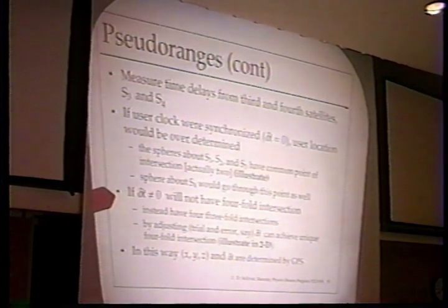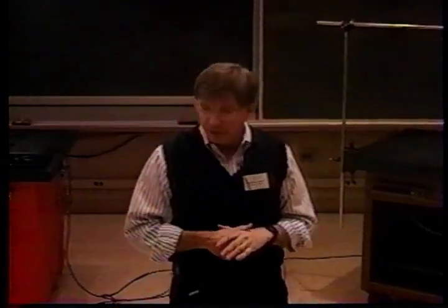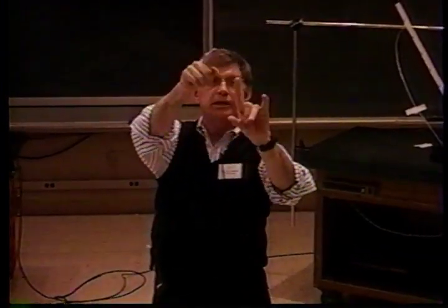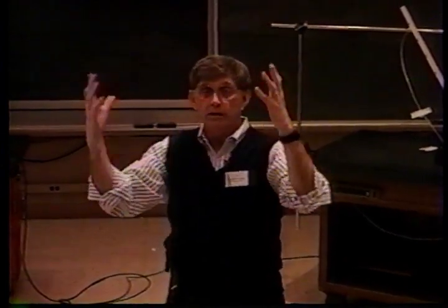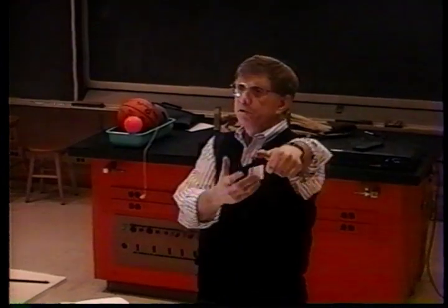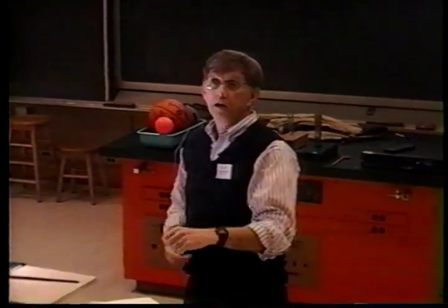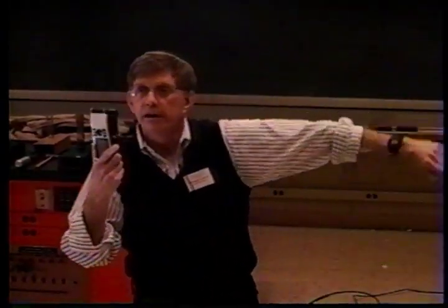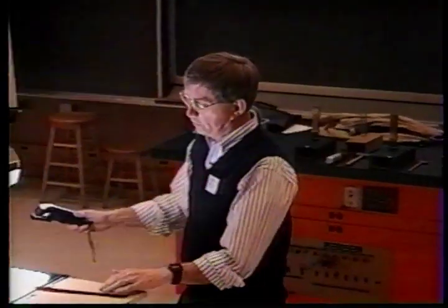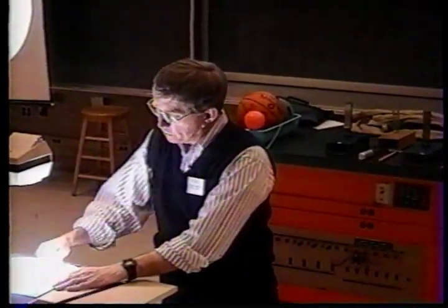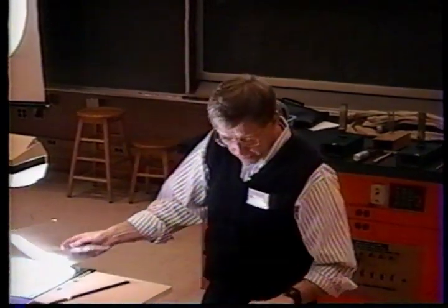And so in that way, you learn from 4 measurements, you learn 4 things, and you should from 4 independent measurements. You learn your x, your y, your z, and the clock error. So now you've got a clock that's as good as the atomic clocks up in the satellites at the price of your $30 wristwatch. The receivers, GPS receivers, mine included, have clocks that are no better than the clock on my wristwatch here. Don't have to be fancy. They can't be terrible, or it would take a long time to find out the right adjustment.